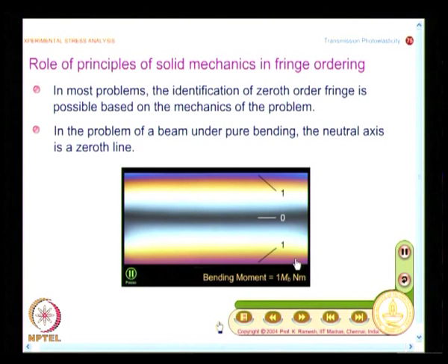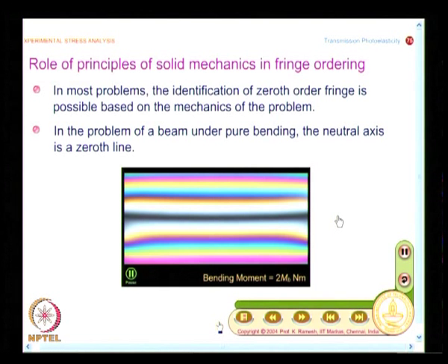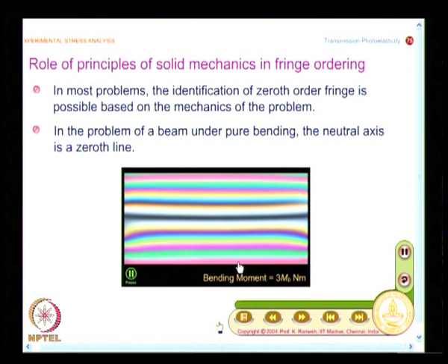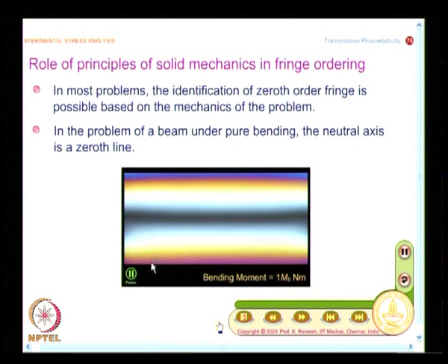and because of this luxury of the multimedia, you can quickly see what is happening in a beam under bending. And what I have here, I have this zeroth fringe order at the center. While we looked at beam under bending, we never bothered to look at how, as the load is increased, this remains stationary.